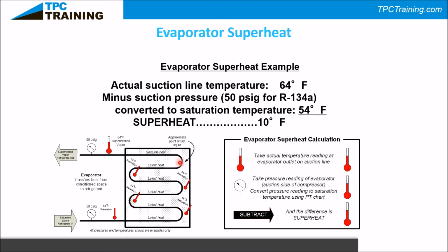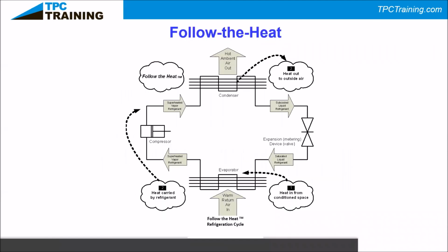Yes. And a symptom of that would be that the superheat is set for 10 and it's rising up too high. So what you would do is take your bulb off of the evaporator and dunk it in hot water and watch to see if the pressure on the blue gauge of your evaporator would change. If it's not changing, then that means that bulb has lost its charge. And once it's lost its charge, you're going to have to replace the whole metering device in order to fix the system. Does that answer that question, Ryan?